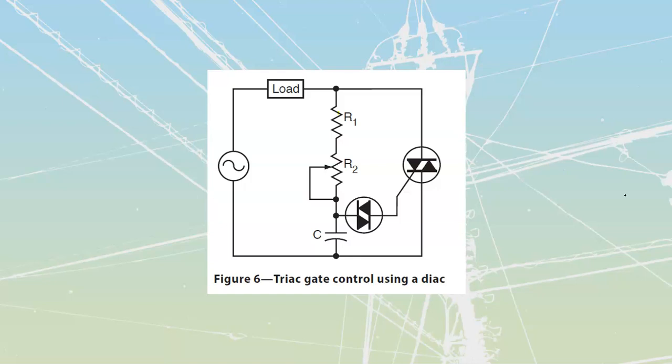There's a bunch of industrial control signals, but sometimes you're just going to have a customer and you know that if you leave it the way it is, he's just going to screw that thing up. So you place another resistor in line with it so they can never get below certain values inside of there. Sometimes you do this inside of software, other times you'll do it inside of hardware by physically placing this resistor in here. Okay, one last thing before we do the actual analysis on this.